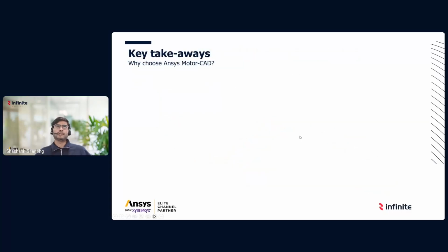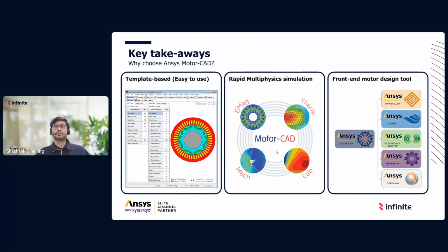But finally, coming to the key takeaways here. When starting an electric machine design, you always start with a large design space and then narrow it down to the specifics based on your requirements. So it's an iterative process, and considering geometry parameters, you set the winding configurations, material data, and the multiphysics performance output of the machine is obtained. And once these are done, you can later go for optimization strategies with OptiSLang, let's say, or moving into Fluent for some more detailed CFD analysis.